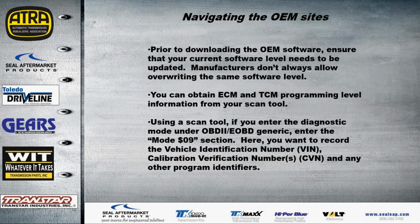if you take just a typical scan tool, doesn't have to be OEM, you want to go into the generic side actually, OBD2 or EOBD generic, Mode 9 section, and once you enter into that area, then you can view the VIN number information as well as the calibration verification numbers and any other program identifiers that might apply to the modules and the drivetrain. Again, this is a very important step to take just so that we can use this information for comparison.